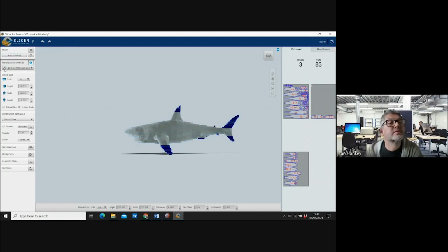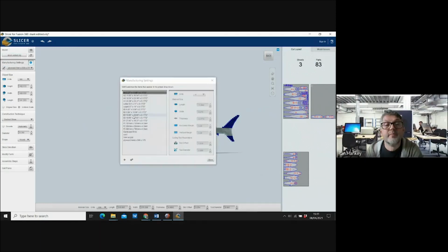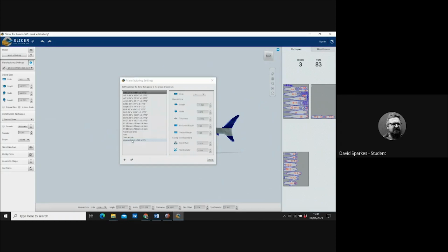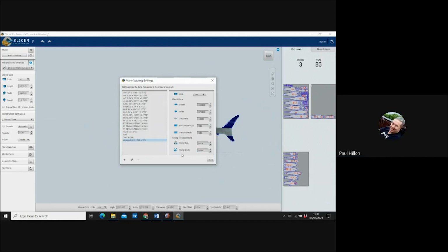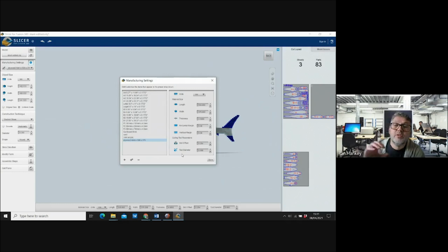Let's go into our editing. I'll just say that mine's been at 0 and I've had no problems with that. Just open the plywood there. And now these are the different things here. We have thickness, horizontal margin, vertical margin, a slot offset, and a tool diameter. Mine's set at 0.2, but it's not coming up. Really, we're not using a tool for this. We're using a laser cutter, which doesn't have a diameter at all.